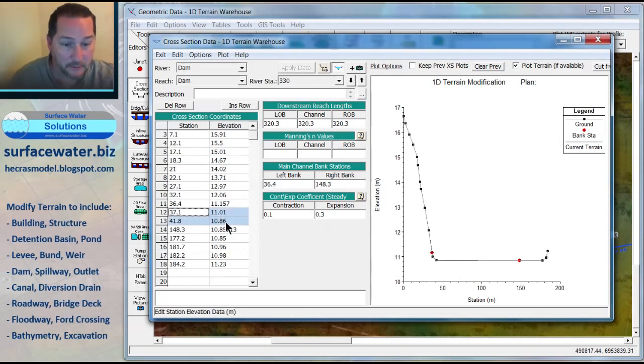I'll do the same thing now here in these other ones just to keep it a little quicker. I'll just blow these ones out and put in maybe 2 sections in between. And I'll show you, you can do it just with a single section as well. So if I go to 50 and 120 and pull this one down to, say, 7, I've got a little trapezoidal section in there.